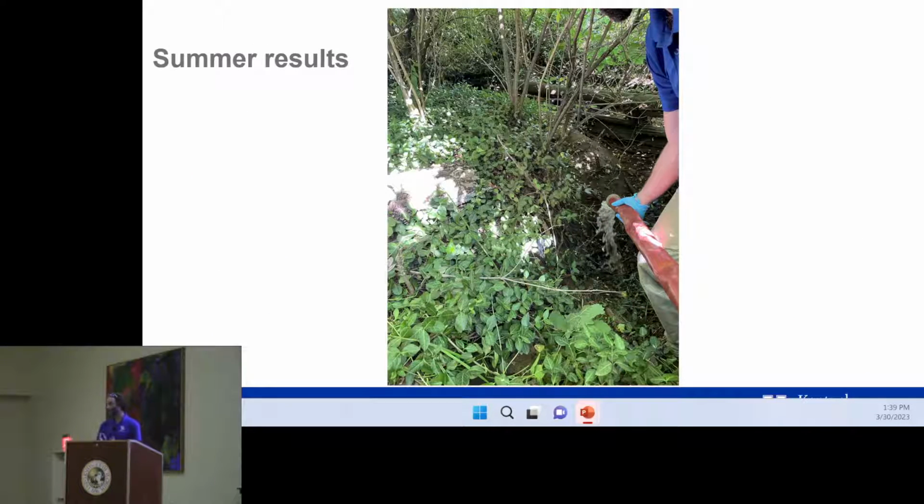We wanted to see what happened in the summer. We came back. There's a lot more vegetation there in the summer. This is pretty much the same angle as the last photo, but the plants take up everything. So in this case, we had generally overall much lower water levels. The conduit is about 100 feet below the surface here. The water level was 15 feet higher in the winter as compared to the summer.